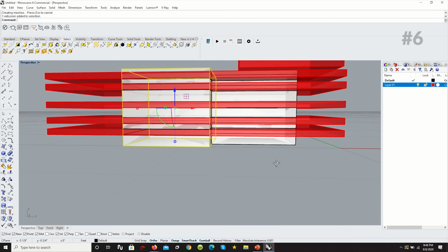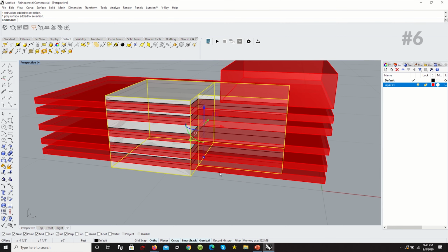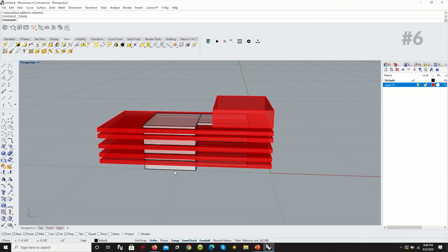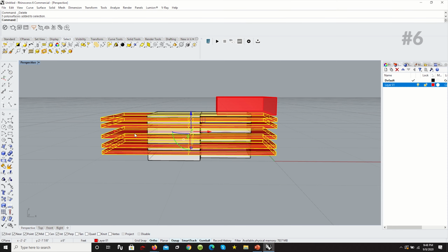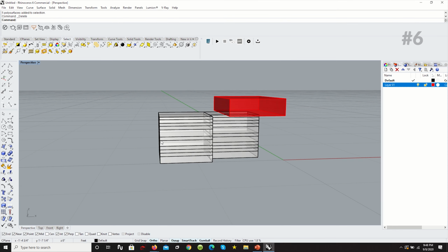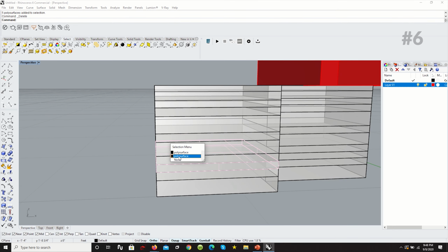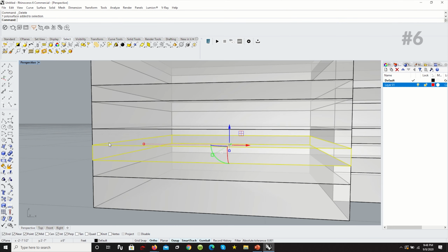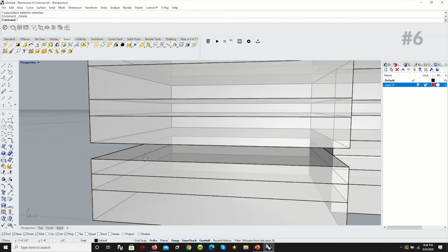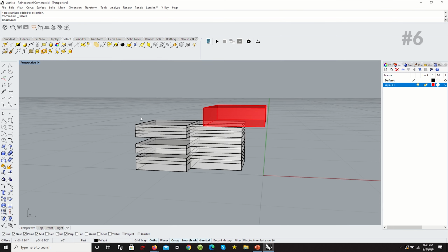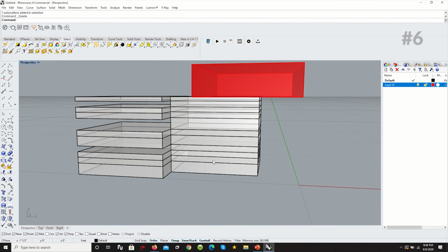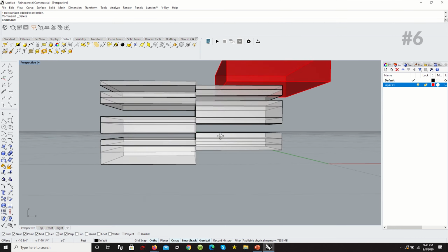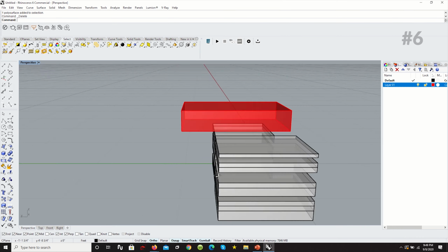So my thing made a duplicate, which might happen on your Rhino. I have to fix the settings. We just have to hit delete. And we can also delete these surfaces. And now look, everything's divided. If I wanted to, I could hit delete, delete this one, delete that one, delete, delete, delete. And we have a very interesting geometry.